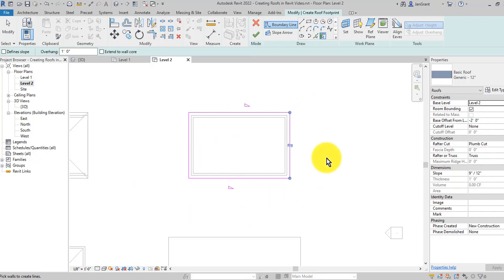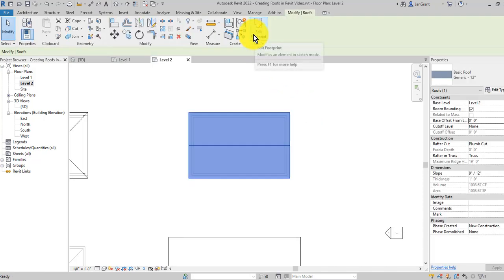Now, like I said, in video 1, we went through this and talked about a few more things. The other thing we want to be careful of is that when you set up some defaults for the project or the part of the roof that you just finished, you have to really watch properties because it still has the -2 offset that we used for the flat roof. So we want to put that back at 0 so that our roof sits at the top of the wall. I'll go ahead and pick apply. Okay, and then pick the green check mark, and because we changed the view range in video 1, you can see the whole roof here.